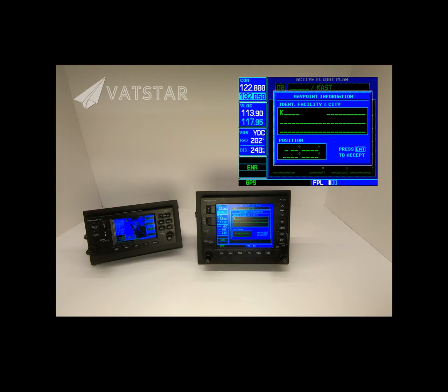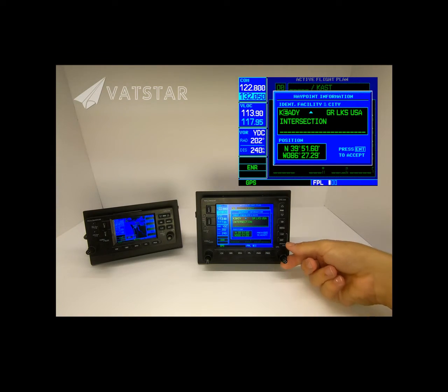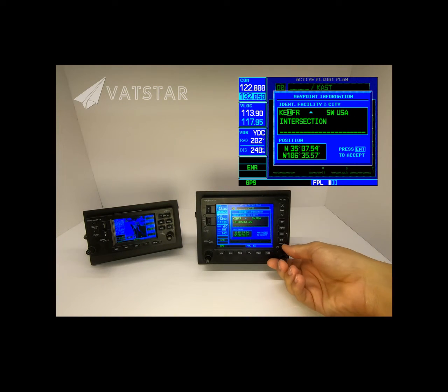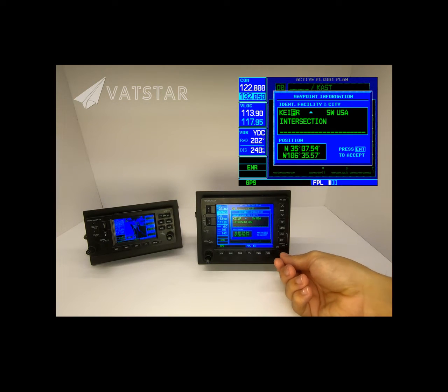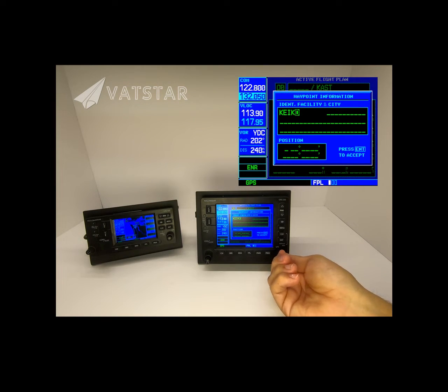Echo India Kilo Oscar. So we're just going to do one knob, the bigger knob, one to the right, since we're going to keep that K in there, and we're going to use the little knob to look through the alphabet, right? So the next one is going to be an E. And then once we have that, we're going to use the bigger knob, the inner knob, and push it one to the right. And we're going to look for the I now, India. Perfect. Outer knob again for looking for Kilo again. And then the last one is Oscar. So O.